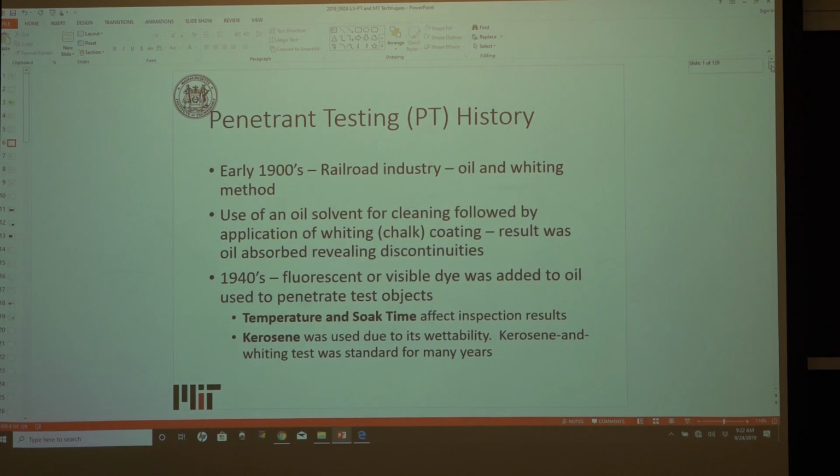What they would have to do is, it was very much reliant on the surface prep. If you travel on railroads often, you will see what are known as flat spots in the rail, where the wheels and the rail contact each other from friction, or sometimes if there are leaves or other things on the rail itself, it will cause flat spots. And the preparation on the rail head is important to the outcome of the inspection.